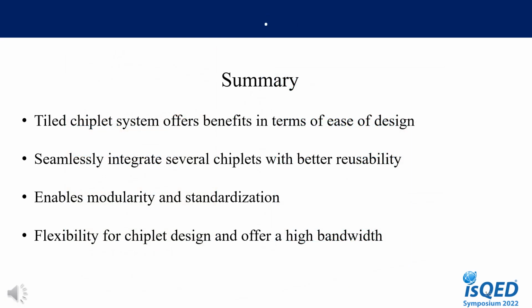Therefore, the methodology for the PBS design for tile chiplet system offers benefit in terms of ease of design, achieving higher bandwidth, and seamlessly integrating several chiplets with better reusability. So in this work, we mentioned the requirements of a passive base in silicon requiring multiple metal layers with wider spacing and higher width to obtain lower communication latency.